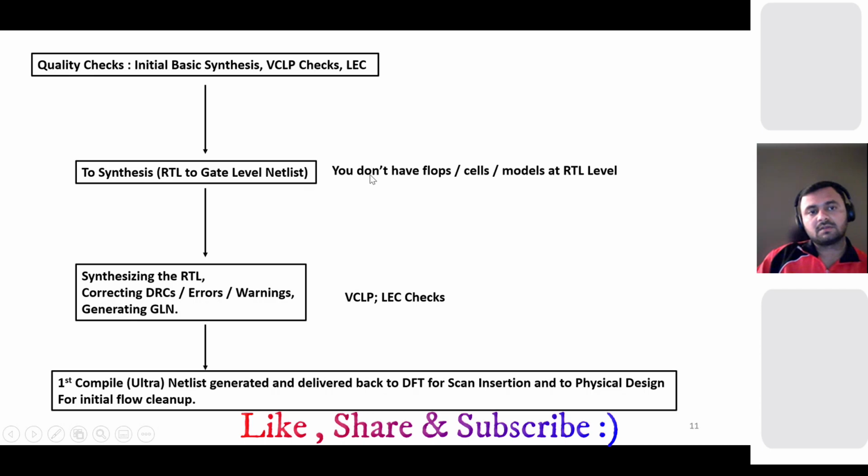The synthesis team will take the RTL, that is the DFT inserted RTL, and generate the gate level netlist. At the RTL level you don't have any flop, cell or model. It's just a behavioral model. Like you might be writing some D flip-flop code using always at posedge or negedge. You don't have any physical flop or cell there. So to map those models, the synthesis team will take your RTL and map it to the gate level, and then they generate the synthesized netlist.